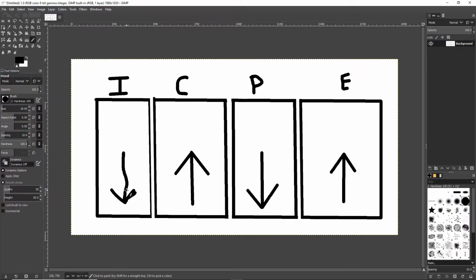Alright, so on intake, we come down, pull air and fuel in. Compression, I'm going to make the piston go up, and that's going to squeeze the air and the fuel. And when we squeeze the air and the fuel, it's going to become volatile. Then, right here in the center, so not during a stroke, my spark plug is going to fire. So we have air and fuel, we squeezed it, the spark plug will fire right here. Now that air and fuel is going to burn, and this is a power stroke because the burn,